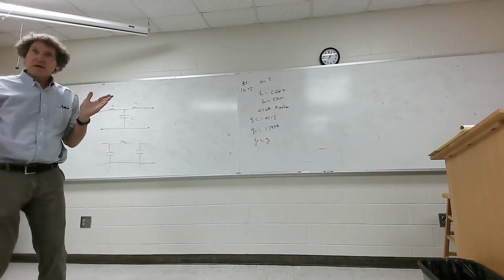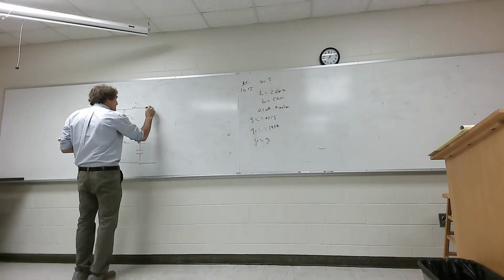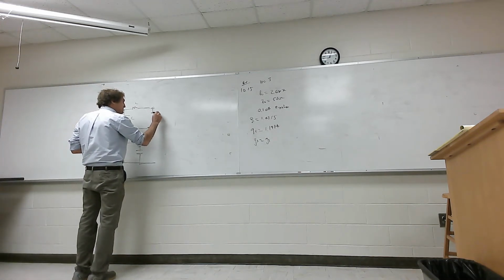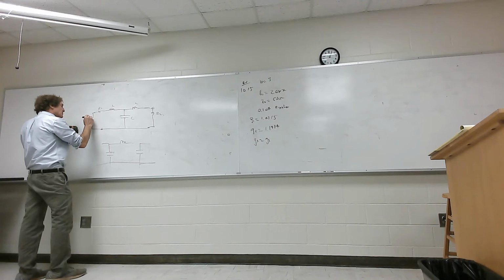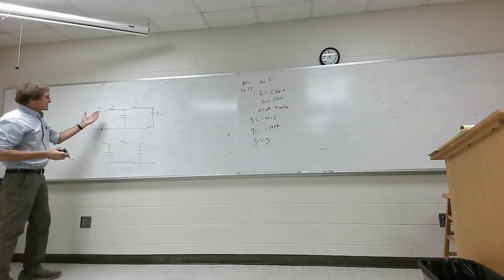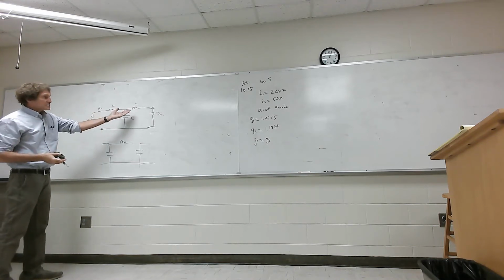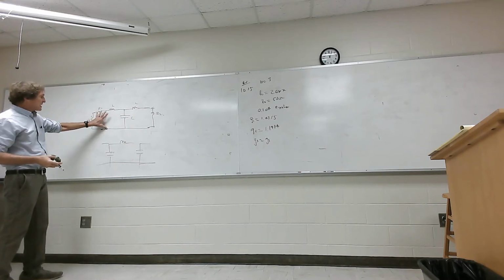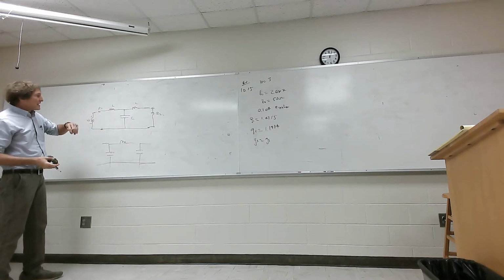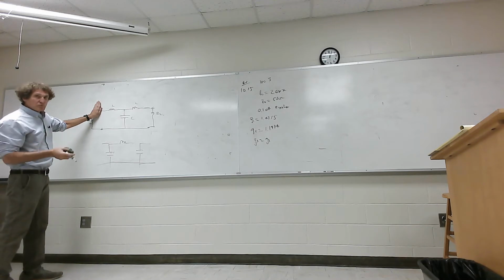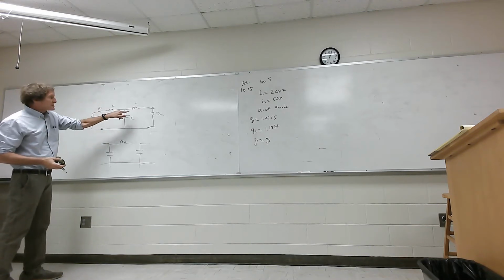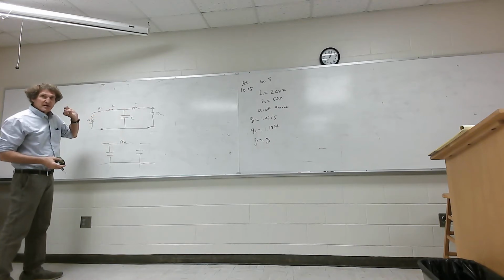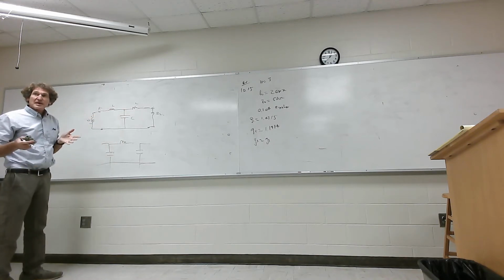If you put a load in here, any load at all, and you have a source resistance, and here you're going to have plus or minus Vs. You can see that at DC, the inductors look like short circuits, so the output is basically the voltage developed here. If you didn't have a source resistance, output would be Vs. As you get to higher and higher frequencies, the impedance here goes to infinity, and the capacitor becomes a short, so you get nothing. It's a low pass by design.